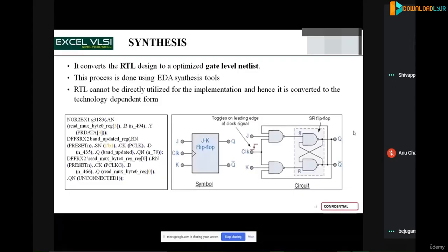Okay, and in the ASIC flow, when you have designed Verilog, you can take that to a 16 nanometer technology or a 10 nanometer technology. You can go and experiment whether you can still do that with the lower technology nodes. The standard cells will be provided by the manufacturer, like TSMC or whichever foundry provides the standard cell libraries.